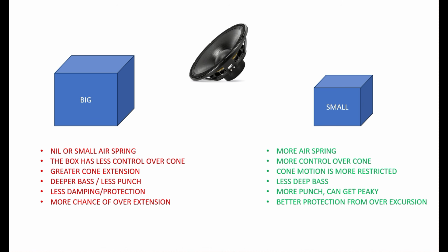All right, so what if you put the speaker in a box that is too big or too small for the speaker's design? We want to get the best response from our speaker, so we want it in a box of the correct size. If it's in a box that's too big, then the effect of the air spring is greatly reduced, or if the box is super big, it will act like it's in free air. Generally, it's a bit like having a soft suspension. The speaker will have less control over the cone.